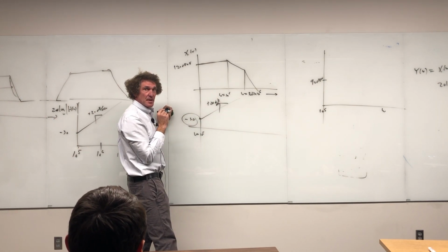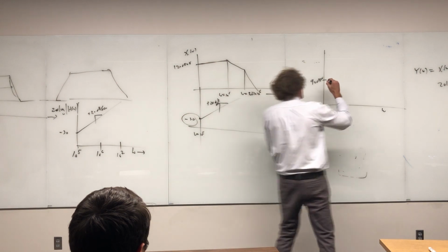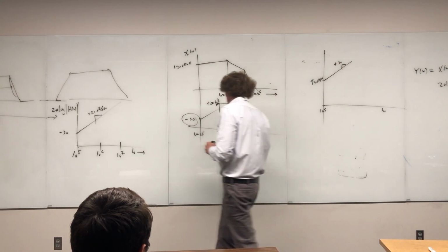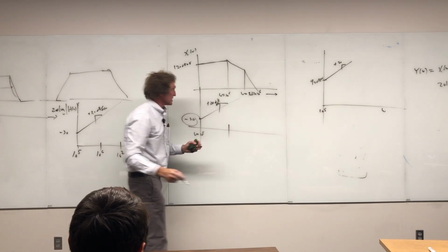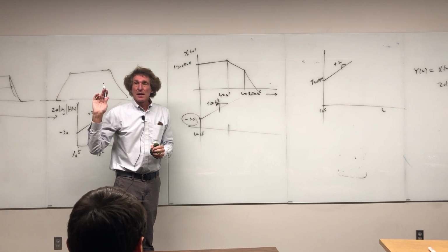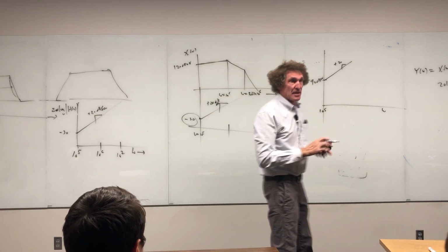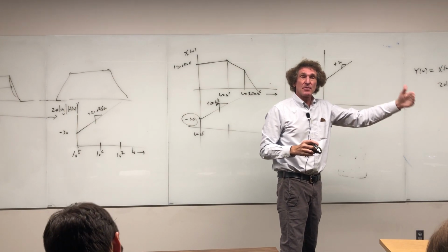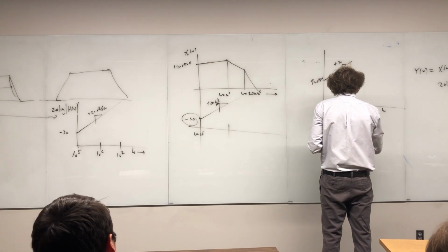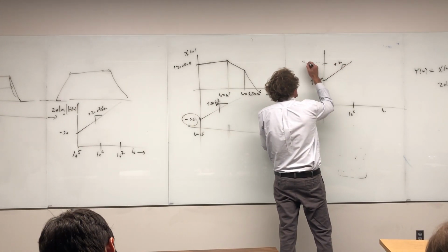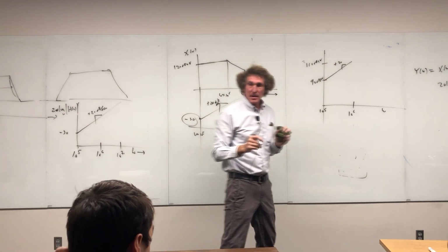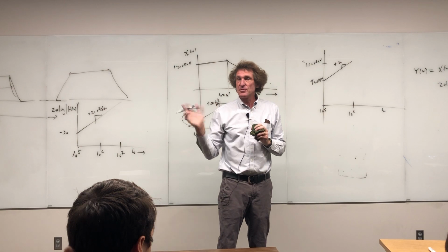Now notice this is flat here, and this is increasing at 20 dB per decade. You all see this? So it's going to keep going up at a rate of 20 dB per decade until I go exactly one decade, to 10 to the 6th. Correct, class? Now, at 10 to the 6th, we've gone a decade in frequency, we've gone up 20 dB. So here, at 10 to the 6th, my level is going to be 110 dB microvolts. Do you all see that, class?